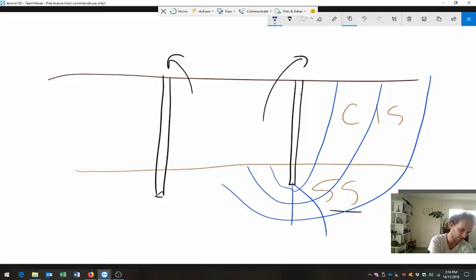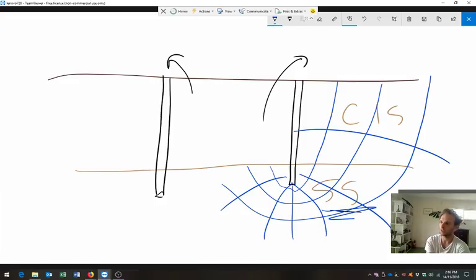We get away with a hybrid basement in this instance because we know our flow net looks a bit like this. It has to flow through this sandstone, and if our sandstone is really rather impermeable, then we would find that we get really low flow. So you could get away with a hybrid basement. That's one example, if you could create a cut-off wall into the sandstone. Otherwise, if your basement's solely in the Coot Island silt and we have a high water table, then yeah, we would probably have to go to a tanked basement.